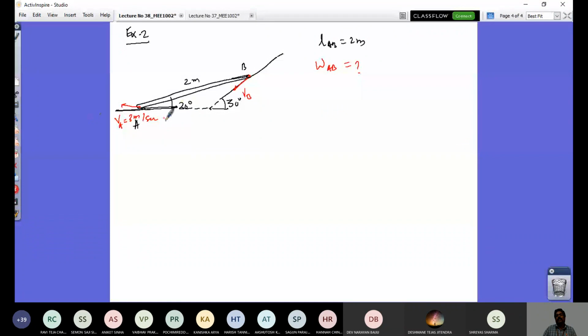But till then, you see this point's velocity is different, and this point's velocity is different, because as a whole, this bar is not only translating, it is also rotating. That's what you have to see. And this motion is what is called general plane motion, GPM. That's what I was telling. So how do you solve this problem? You're asked to get this. Also, you have to find out the velocity of point B, right? And this motion is a complex motion, because this can be looked at in an IC engine example.